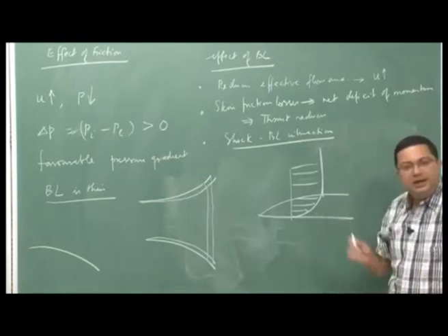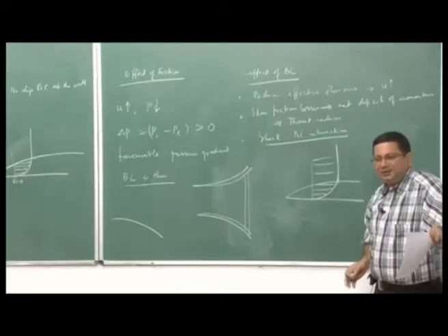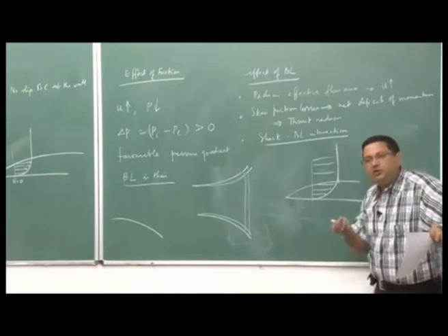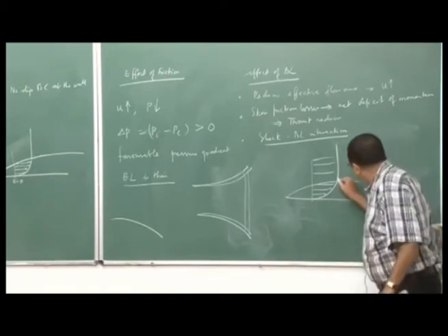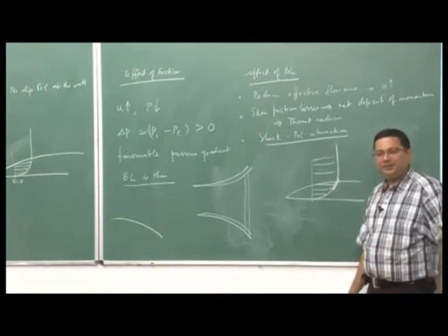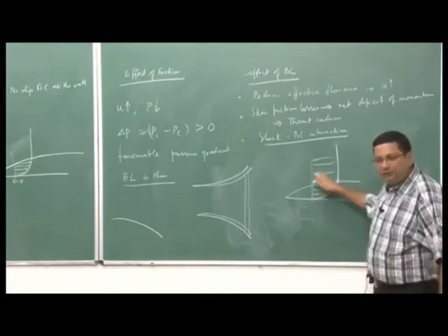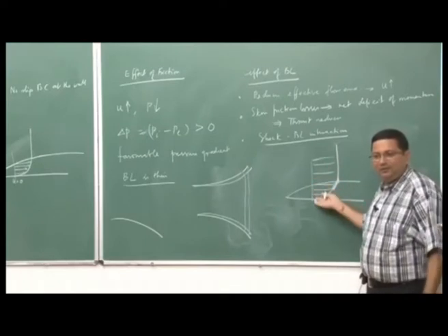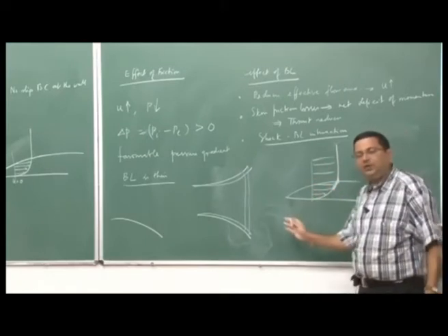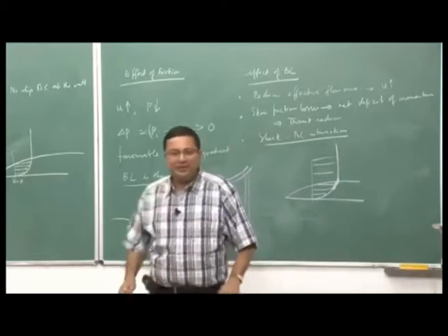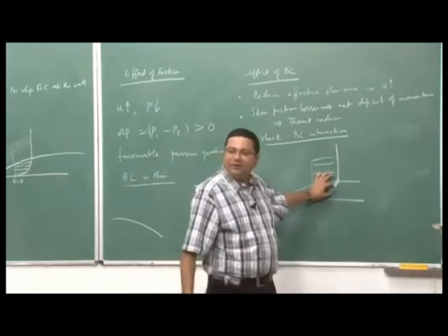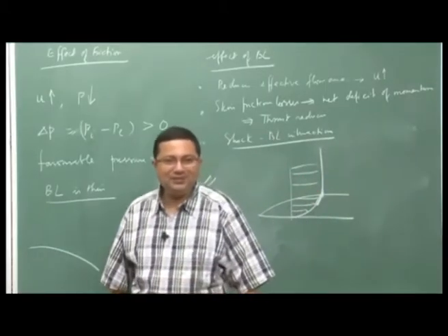There is no change in area here, right. There is no work done, nothing. So, the only possibility is going through a shock wave. So, there is going to be a shock wave here, right. Only then the continuity of the flow will be maintained. Otherwise, rather, shock wave is a discontinuous process, but at a molecular level it is continuous. So, there is going to be a shock wave here close to the wall, right.